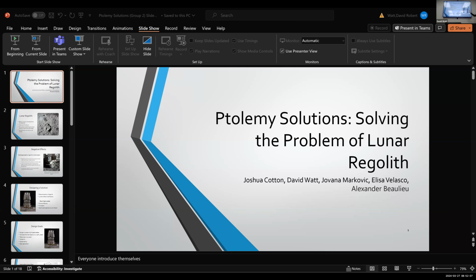So here we have the capsule by itself. We decided on aluminum 7075 due to its high weight to strength ratio and low cost compared to other materials. The capsule is divided into 2 chambers, an upper chamber and a lower chamber. The upper chamber houses the zirconia tarp, and the lower chamber is pressurized and houses the wheel lock mechanism that causes it to open and expand.